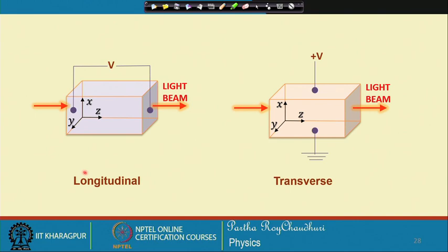So this is the longitudinal configuration of an electro-optic modulator. You have a beam travelling through the medium, and you apply the electric field in the same direction, but this has some inconvenience regarding the direction in which you have to put an electrode. Usually a small hole is placed, or sometimes transparent electrodes are mounted, so that the propagating electromagnetic wave is not obstructed.